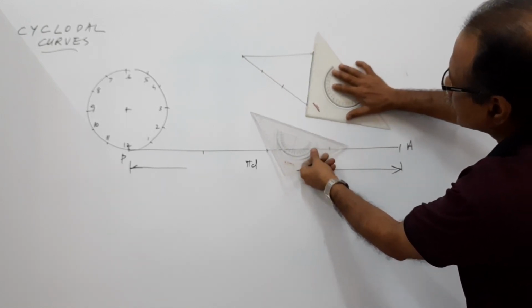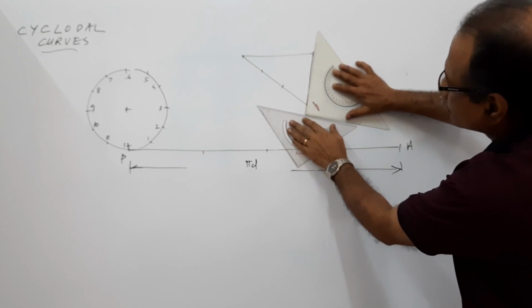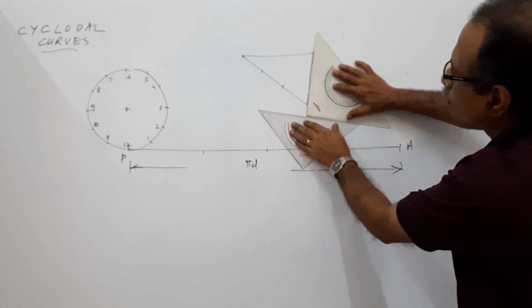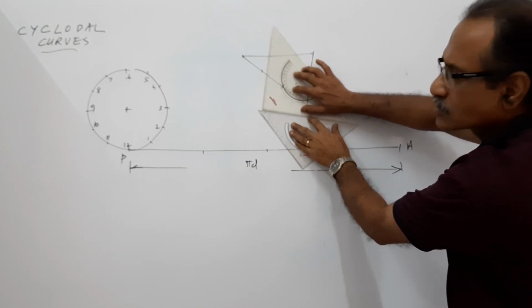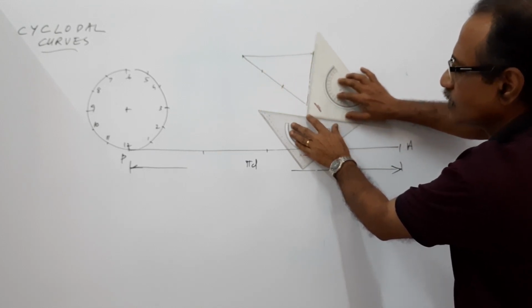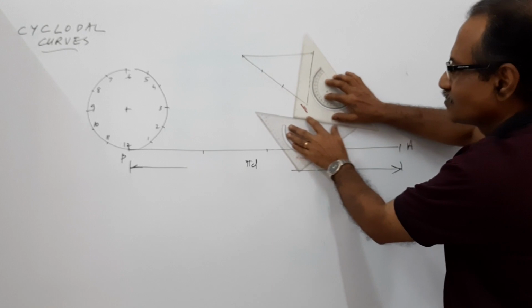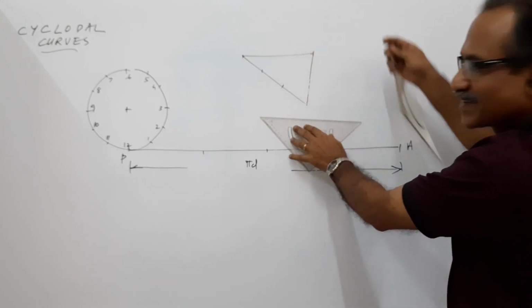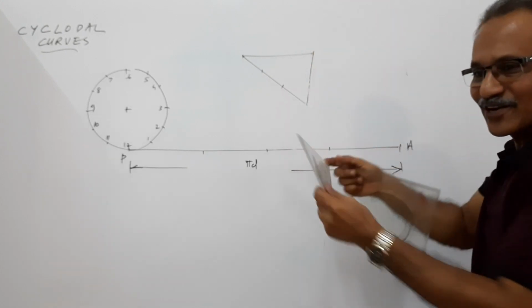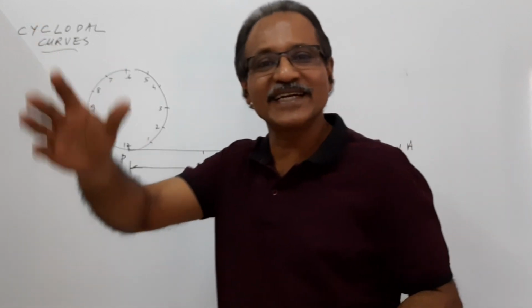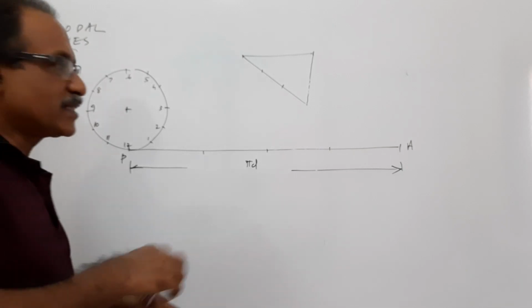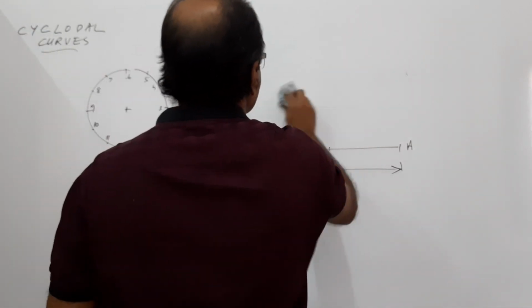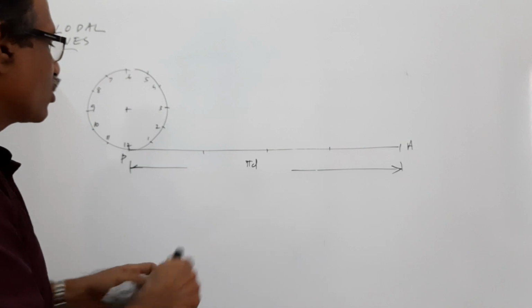Keep this side here, lock the mobility of the other side, then move. Draw lines. Agreed? Some people move both. Wrong. You have to keep one side locked and the other side can be moved. You know those things, I am just explaining, however. So you can adopt that method to divide this pi d into 12 equal parts.